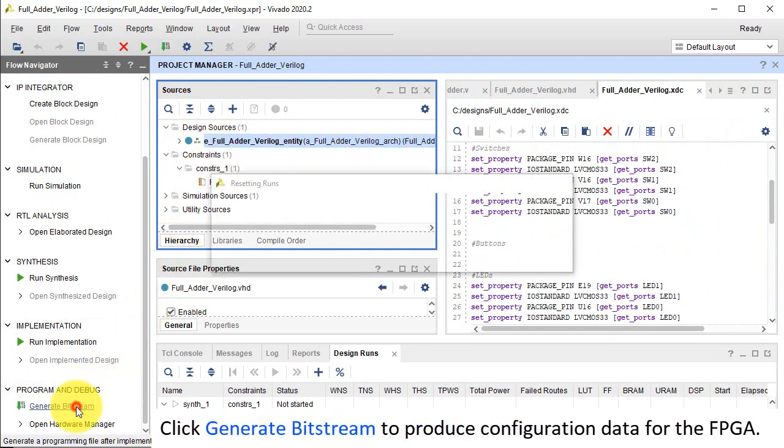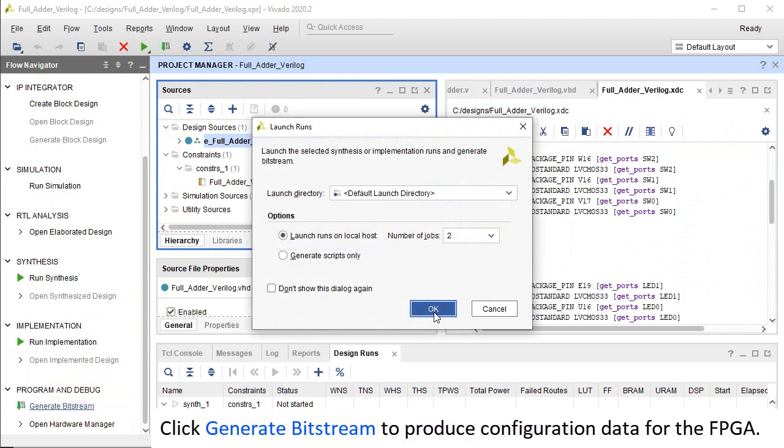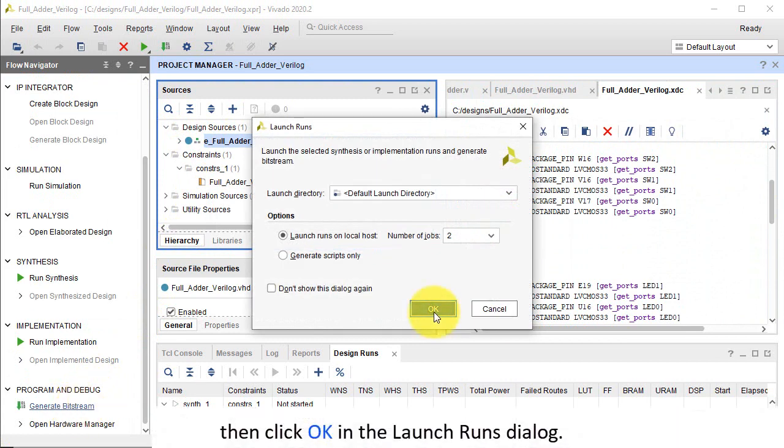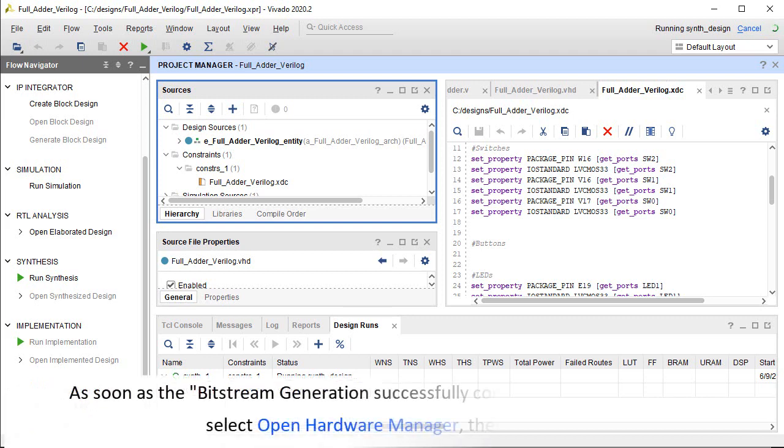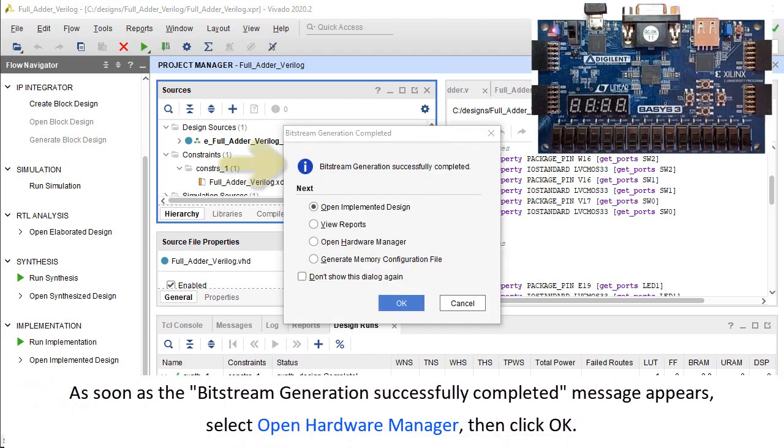Click Generate bitstream to produce configuration data for the FPGA, then click OK in the Launch Runs dialog. Now connect Basys 3 via USB with the Vivado machine and turn the board on. As soon as the bitstream generation successfully completed message appears, select Open Hardware Manager, then click OK.